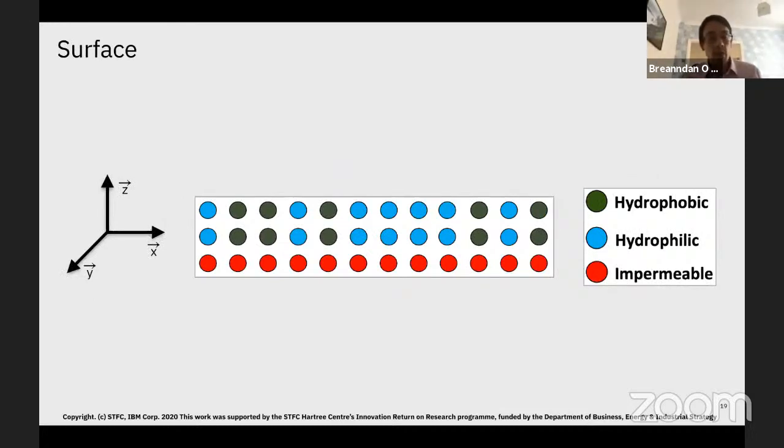And of course, we also modeled the solid surface in the study. So we have a cubic lattice of frozen DPD beads. Now, these DPD beads interact with all other DPD beads in the simulation within their interaction cutoff, of course, but they are frozen and therefore do not move. And this cubic lattice is 3 layers deep.